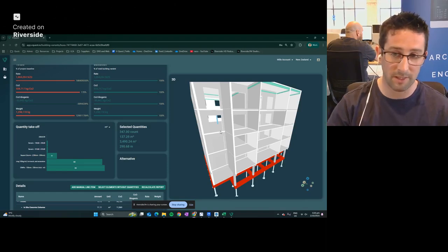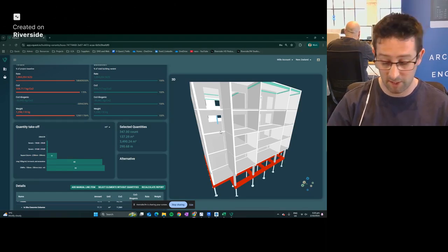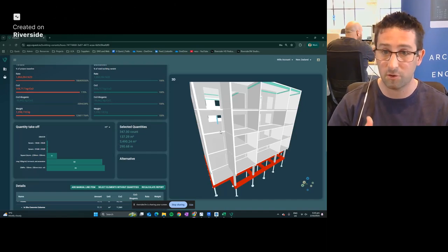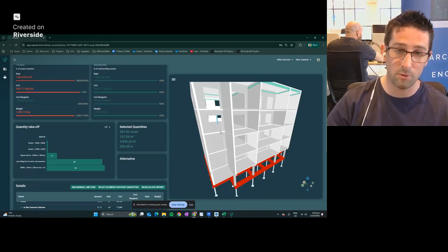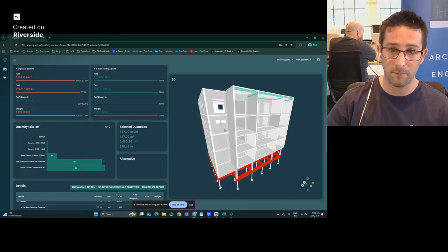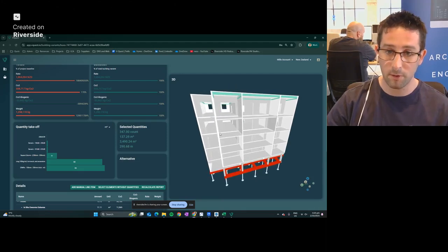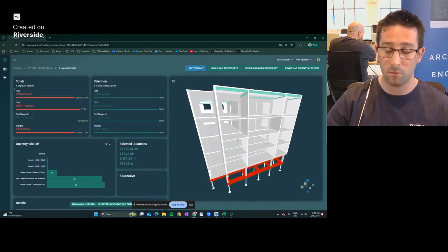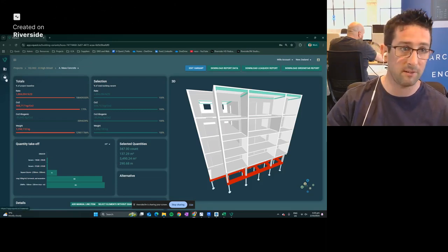I'm going to have to model in a floating floor for acoustics, which has rubber cradles, battens, insulation, strand board flooring. So all of that you do not have to do. You can simply copy that floor, put it on a different layer, the concrete floor. Don't worry about the thickness of the slab. Don't worry about modeling the rubber, the battens, the insulation.